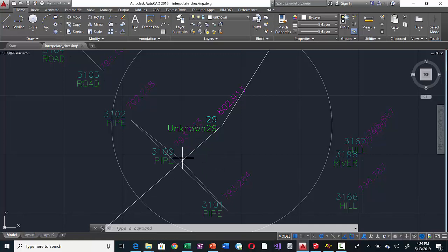So the elevation of this top point is higher than the elevation of this point. According to interpolation, if this point has higher elevation than this point, then the slope is increasing upward. So if the triangle so formed is quite narrow, then there can be a drastic change in elevation while going over longer distances. So if there is a small increase in slope within this distance, then if we are going to this point, there will be a vast difference in elevation. So it came to be 802.913.